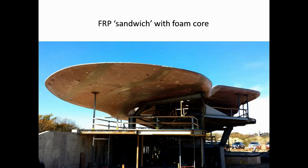And now we can do it with plastics, of course. FRP stands for fiber reinforced plastics, not fiberglass. When we talk about plastic buildings, we're not talking about the plastic that ends up in the oceans. We're not talking about fiberglass, because fiberglass is the tensile reinforcing of plastic. We will talk about plastic in detail at some point, but suffice to say, it's got a foam core, and around that core is resin, which stiffens the material. So it's another kind of stressed skin structure.